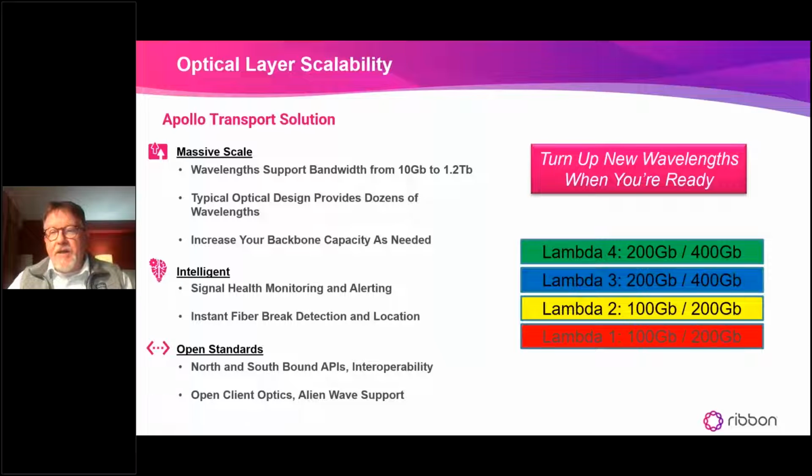And it'll tell you right away if there's a break, if there's an error, if you're getting some type of reflection or what have you. So OTDR and then signal health or fiber characterization, both are in-service tools that obviously allow you from your desktop to diagnose and get a remedy on the way if someone gets crazy with a backhoe in your outside plant somewhere.